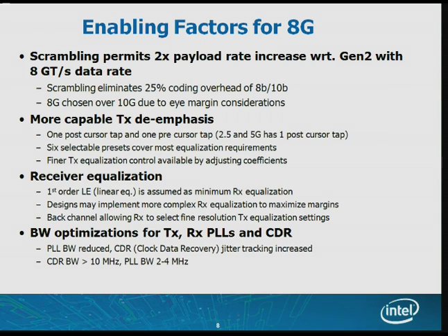PCI Express on day one relied on 8B/10B. That was a technique developed and, I would say, very mainstream in the industry. We delivered 2 generations of PCI Express using that mechanism for encoding, and realized that in the third generation, if we want to make a good trade-off between the complexity of encoding the information and how much we push people in terms of signaling rates, we should take the compromise and require a new encoding scheme. That makes backwards compatibility a little more difficult, because you'll basically be dealing with a bimodal type of interface, but we felt that was the right choice.